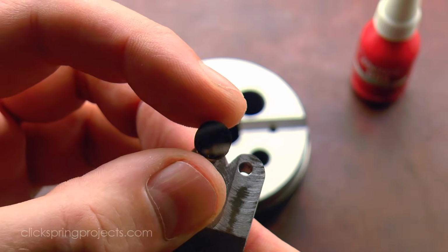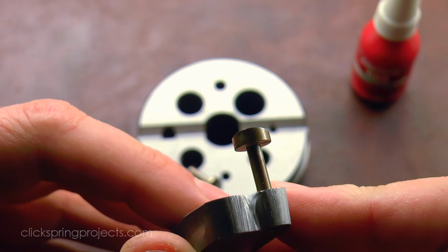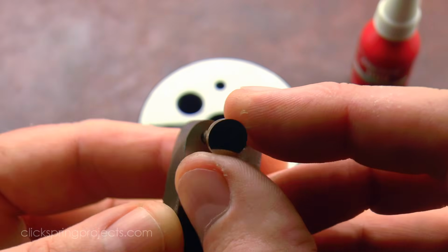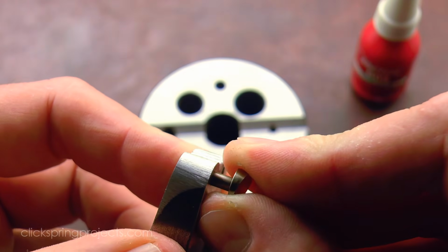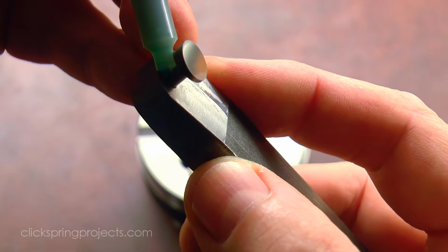The button cutters are then manually positioned on the shank, ensuring a 45-degree rotation of the high point of each button towards the centre line to make the most of both the rake and the clearance angles during the cut. And although it might look difficult to ensure correct positioning, in practice it's fairly straightforward.